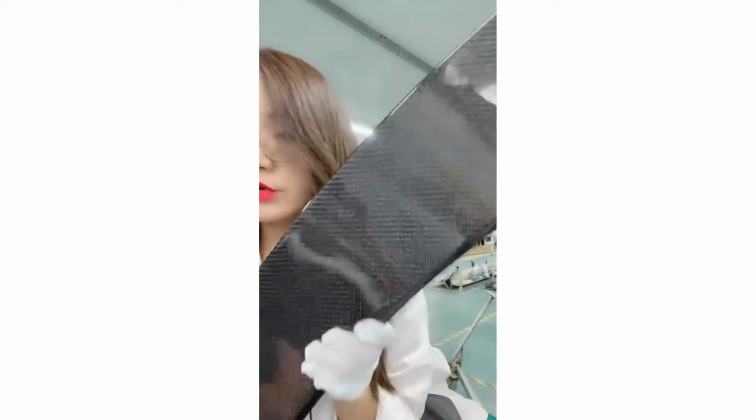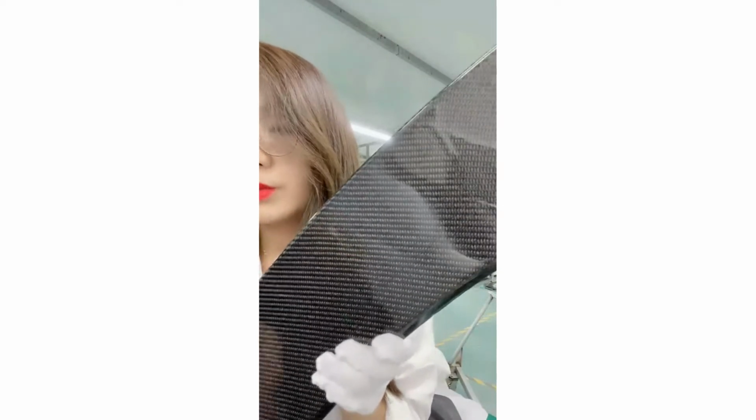Typically, a dry carbon fiber cloth is placed into a mold which has been coated with resin. Then the cloth and the resin are sealed into a vacuum. The vacuum pressure impregnates the resin into the cloth, basically encasing it within the resin and giving it the sturdy structure most people associate with carbon fiber. The process leaves the fiber with a glossy appearance. However, this can be altered by using a matte layer or sandpapering.